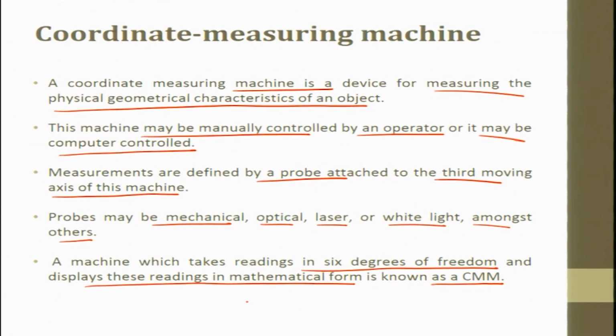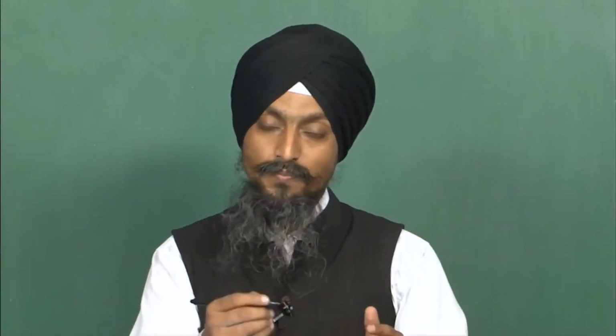If we know that there is a structured form, we can select it beforehand, that okay, this is a circle that we are going to measure. For a circle, a minimum number of points is required to measure. For a plane, 3 points are required to define a plane. For a cylinder, 8 points are required. For a cone, 8 points are required. So I'll come to them.